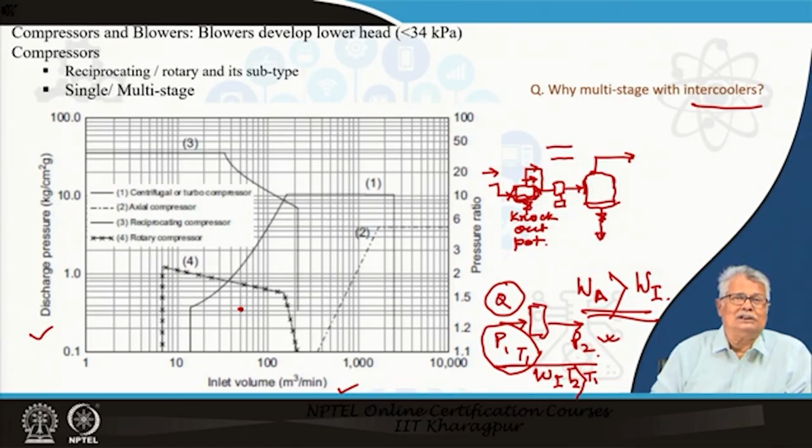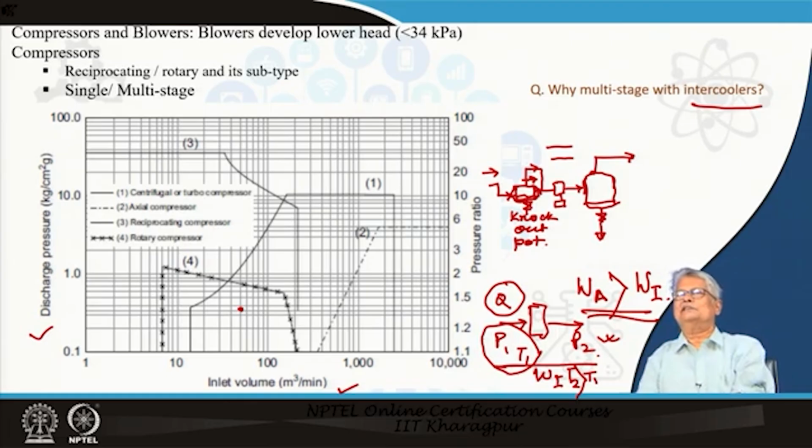It is not isothermal definitely, but ideally what is isothermal? Isothermal means I increase the pressure by a very small differential amount, cool it down to the earlier temperature, increase the pressure again, and this I repeat an infinite number of times in order to reach from a pressure P1 to the final pressure P2. Instead of having infinite numbers, if I have such intercooling and adiabatic compression over finite interstage compression ratios, that is closer to what you have in isothermal compression.